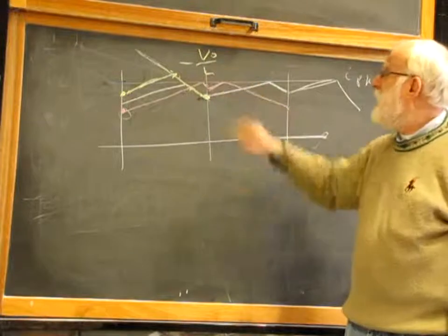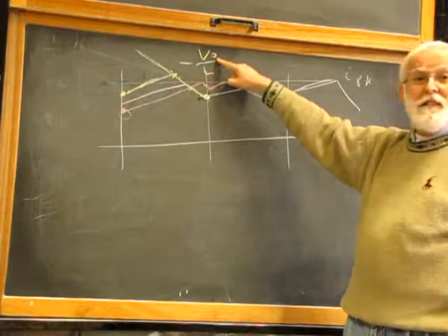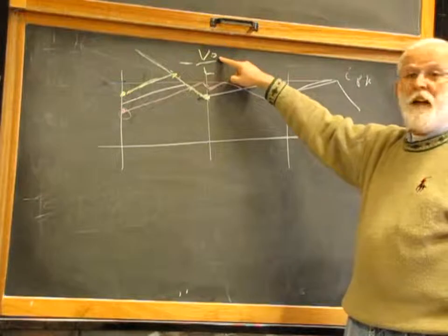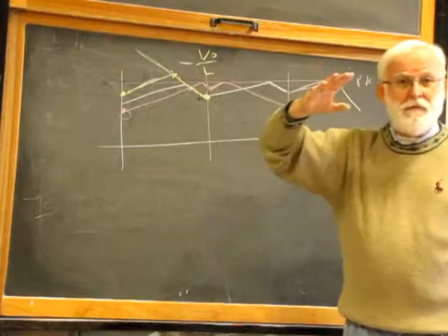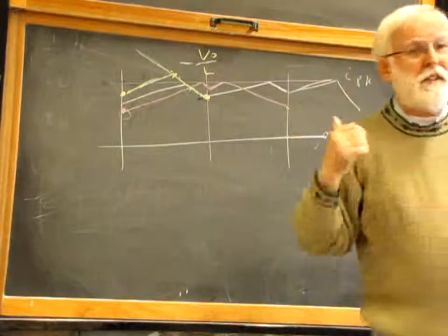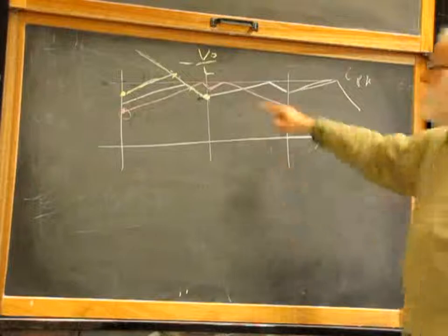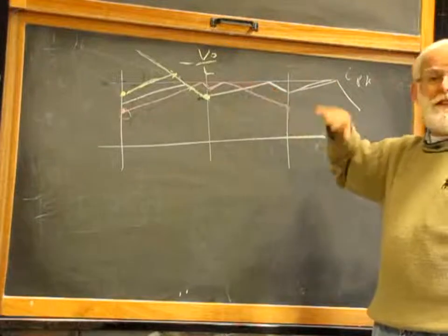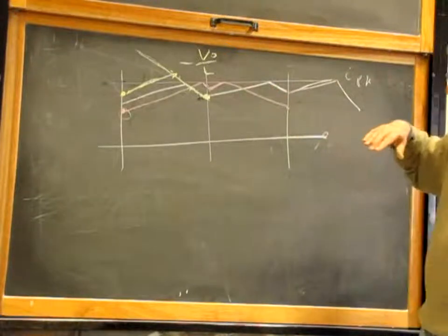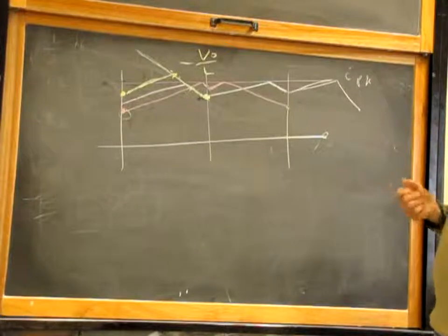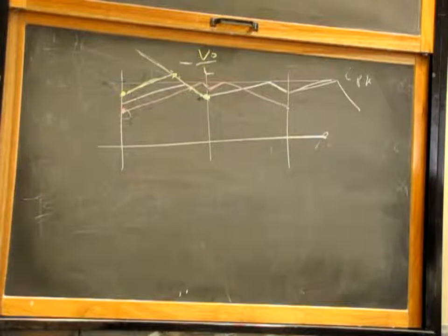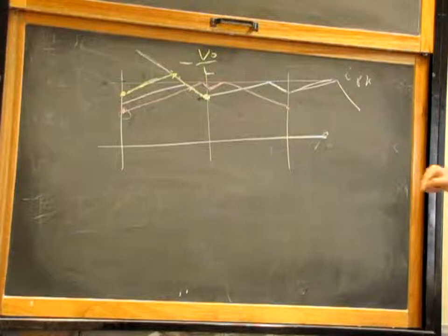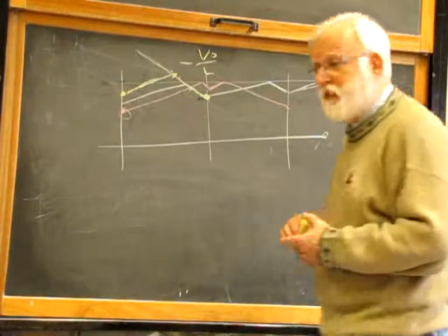compensation slope. And observe that it's nice in buck converters that output voltage is constant most of the time. So this compensation ramp has a fixed slope, and you can add it as we did the last time, not on the controller voltage, but on the other side of the comparator. So we add it on the voltage we read from sensing, current sensing. Okay? Compensation ramp needed for current mode if your duty cycle is larger than 50%.